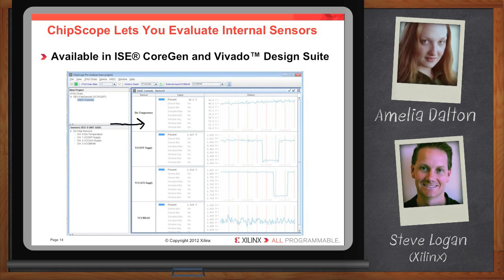die temperature and the three main voltage supplies that we monitor. So those are VCCINT and VCCAUX and VCCBRAM. And you can make sure that nothing funny is going on with your power supplies. Nobody's trying to hack into your system and yanking the power supplies around more than they should, or that the temperature's not skyrocketing, or something shorted or something funny's going on. Good. So you can monitor all that inside ChipScope. And then like we show here, you can also test these voltages with the AMS platform. And so that's what we've got here, where you see the VCCINT dropping down and then picking back up, and the same thing with VCCAUX.